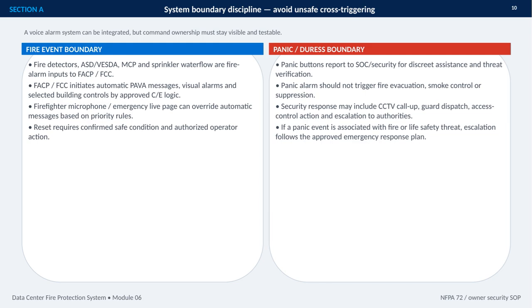Reset is not automatic. It requires a confirmed safe condition and action by an authorized operator. The panic and duress boundary is intentionally separate. Panic buttons report to security or the SOC for discrete assistance and threat verification. They should not trigger fire evacuation, smoke control, or suppression.